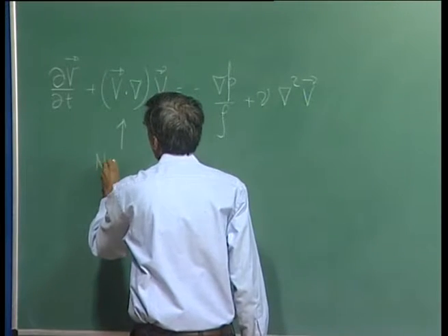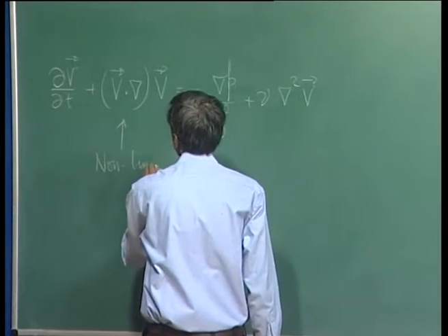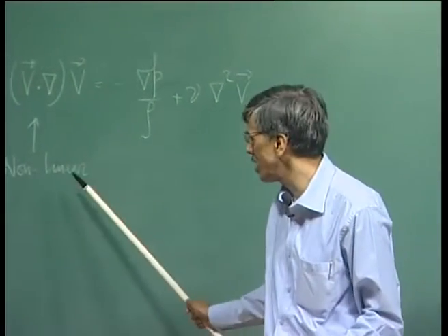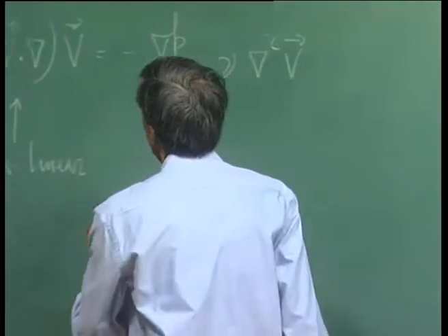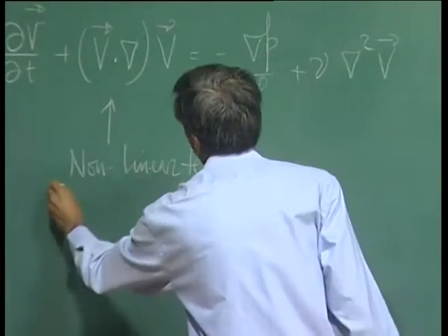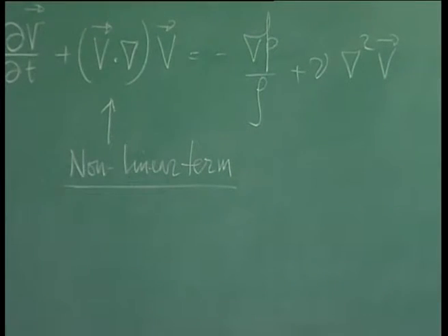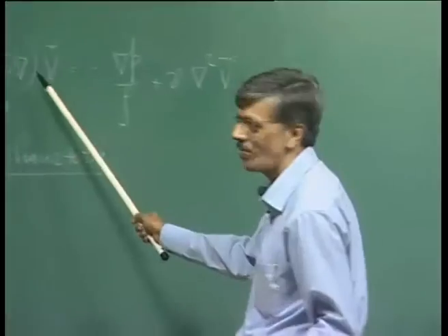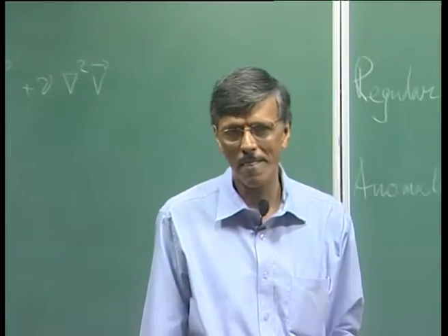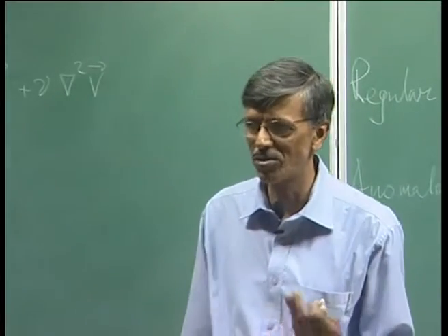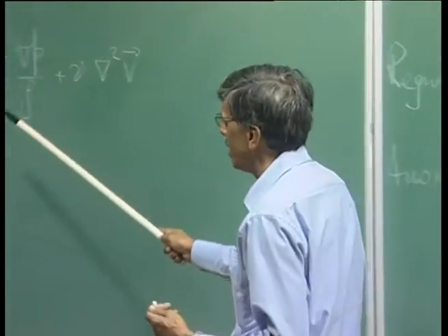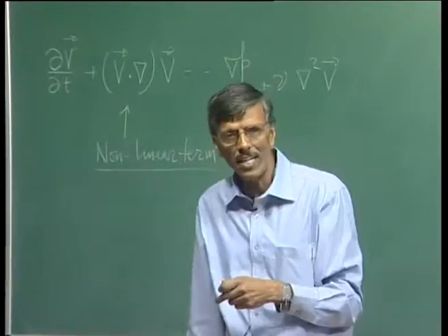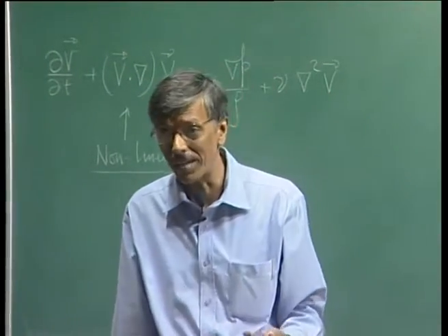Of all the terms that you see, this plays quite an interesting role. This is your nonlinear term. Well, if you are a mathematician, you would say it's a quasi-linear term, because the highest derivative is second, and that's why it's linear. But this is a nonlinear term that plays a significant role in determining the dynamics. We have already seen that all instabilities do start up from here. Why? If you recall, we have written down the Navier-Stokes equation in rotational form. What happens? I can write it down in terms of v cross omega and gradient of v square by 2. Okay? So, we could do that.